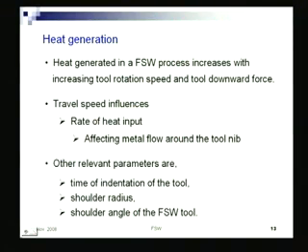because the molten slag may remain entrapped, when it should float up. When the welding is being done, there is a churning action going on in the molten metal. In the churning action, the metal is moving about, the molten slag is moving about, they are all mixed. So it should have time to float up. Now if I move the heat very fast, it will solidify, right? So all those defects may occur.